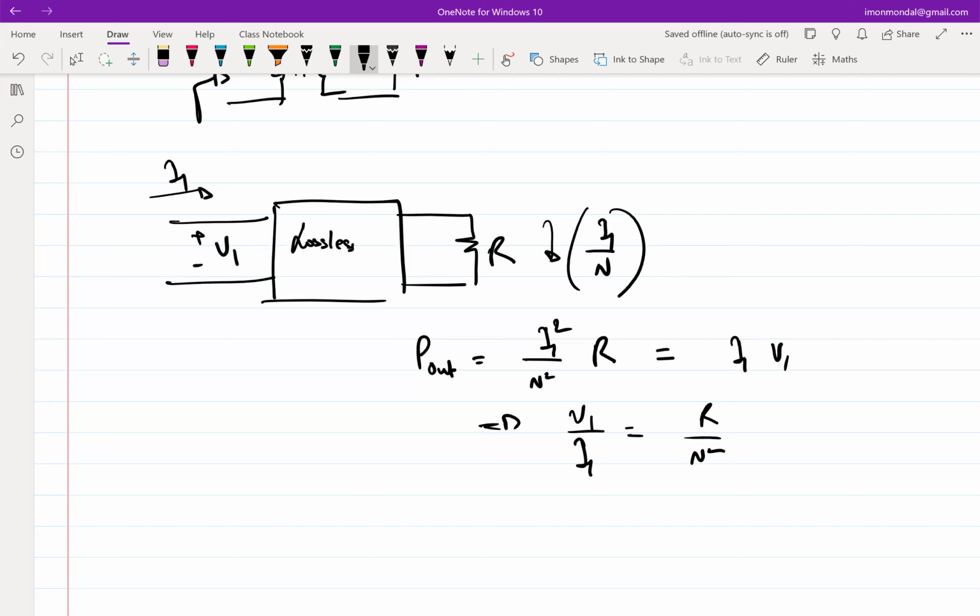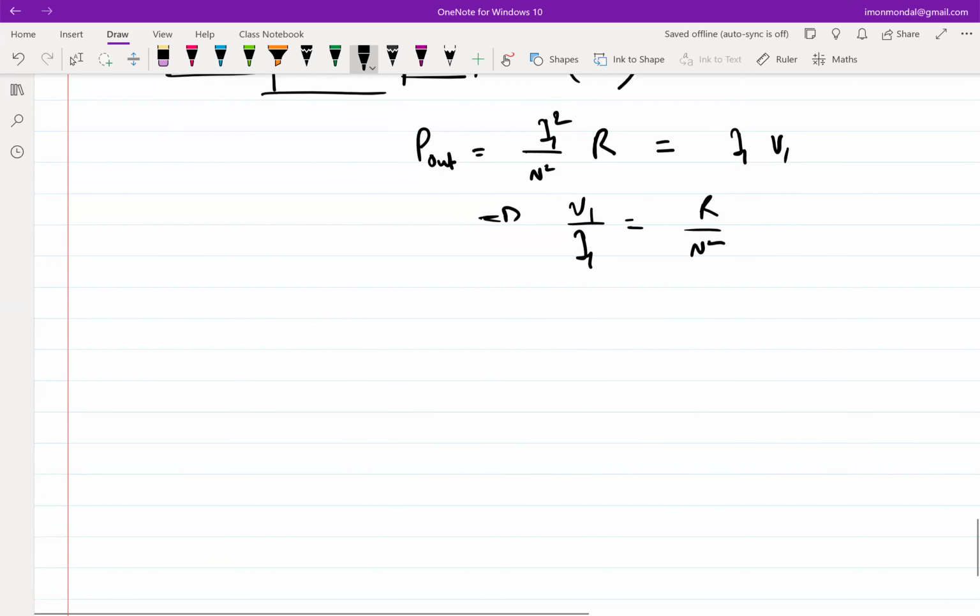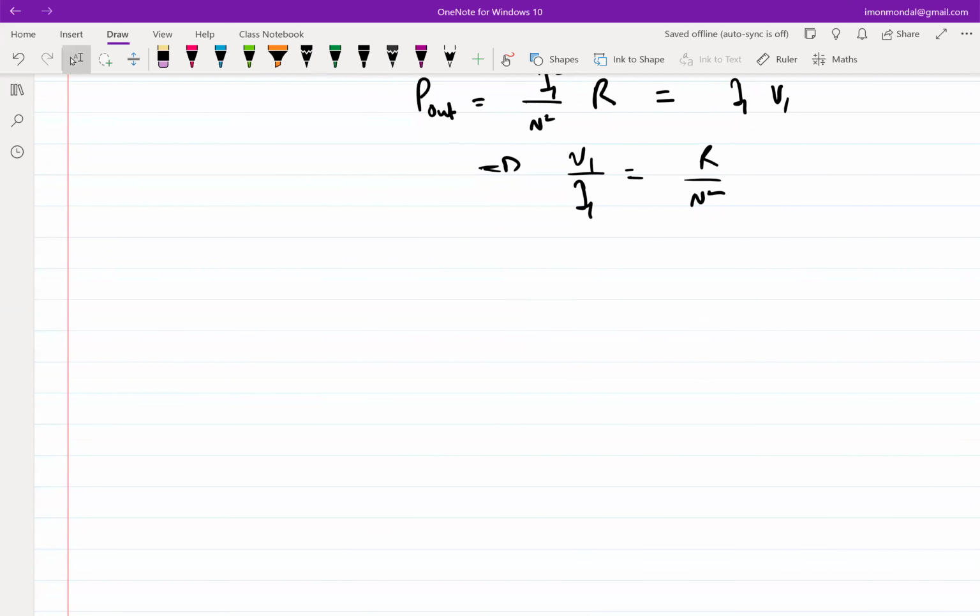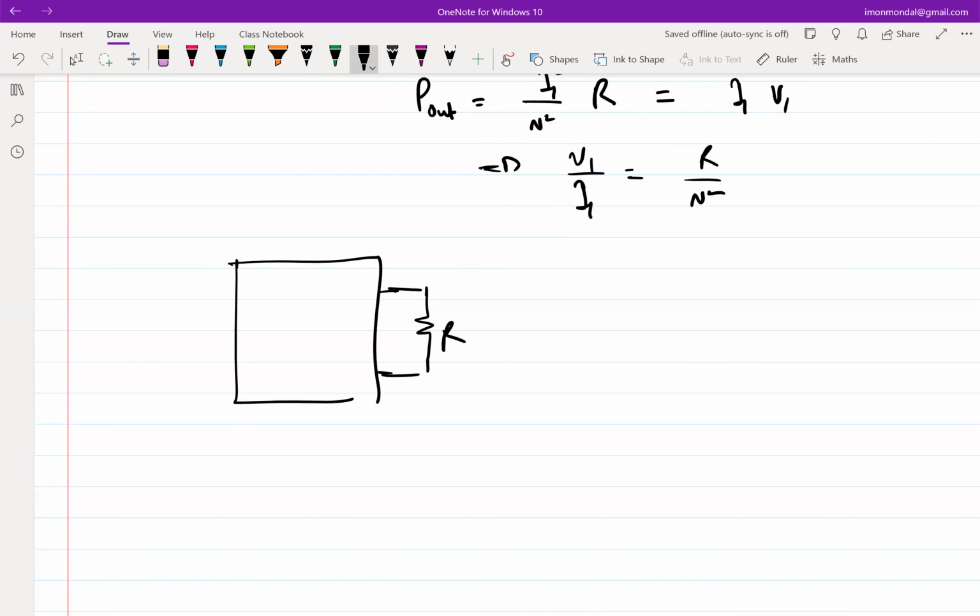Right? So you start your thought process from assuming that you want to step down the effective current going into port 2. Right? So now tell me a circuit that can do that. So I have R. I have to put something here. Forget about the resonating part, we'll think about it later. What can I put here so that if I put in a current source I1, the current through this will be a fraction of I1 at some frequency omega, obviously not DC.